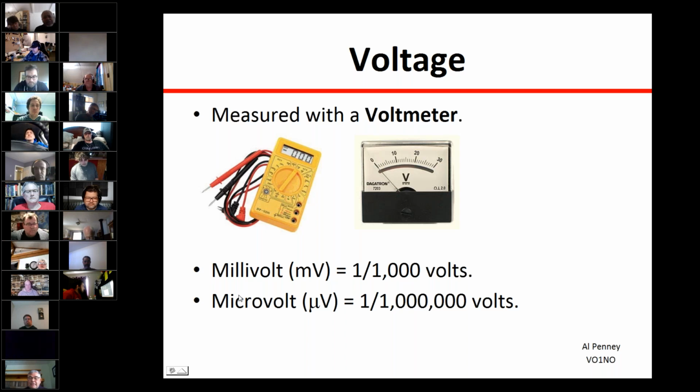Do you think there's any device which can help us calculate both amperes and volts in one device? Yeah, they're called multimeters, but you'd have to hook them up to the circuit differently, because you measure voltage and current in different ways, at different points in a circuit. Most multimeters are auto ranging now, but if you've got an older one, you've still got to set the right scale.